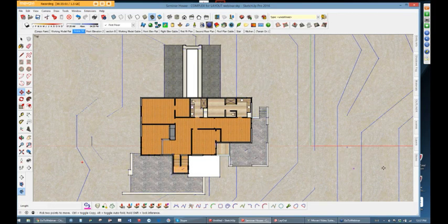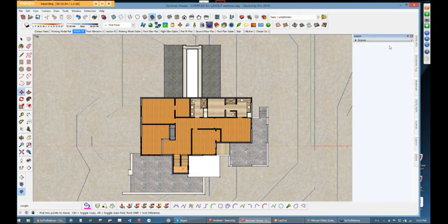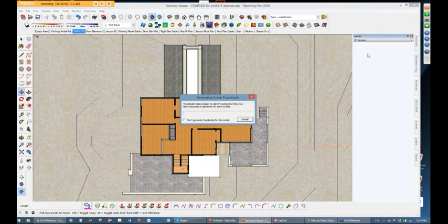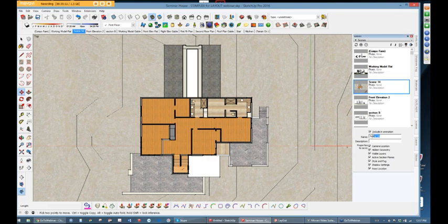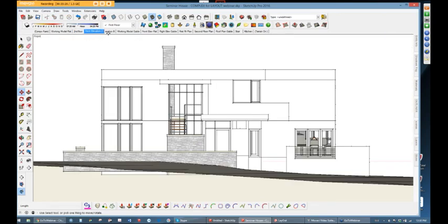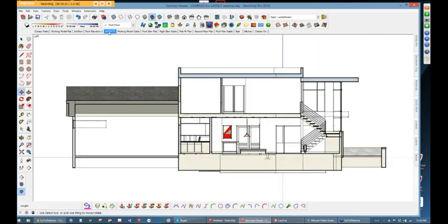Oh, we've got to go to the Scenes tab. If this isn't open, you see that blank space, click on that gray bar up here. This is in SketchUp, remember, we're still there. And second floor. Hit enter. We're done. So now, these things that I've created here as we've gone along, second floor, front elevation, section B, okay? They're all scenes, and you need these when you get to layout.